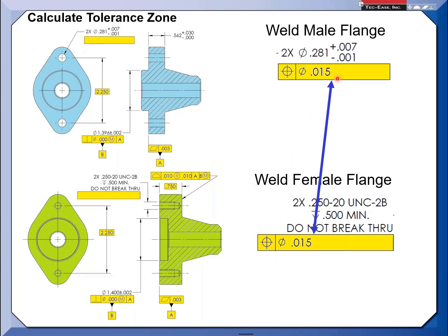So now we have this here, right? Right now, coming up to this point, if I don't put anything here, it's understood rule number 2 would kick in. In other words, if there's no modifier here, these are on what we call an RFS basis. So regardless of feature size, all manufacturing would get would be what's stated in the feature control frame here. Rule number 2 is a default rule when your drawings are in accordance with 14.5.